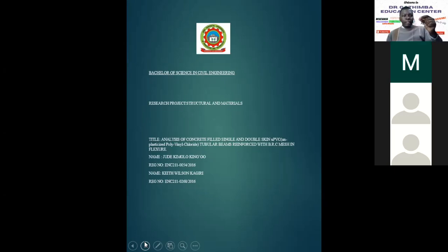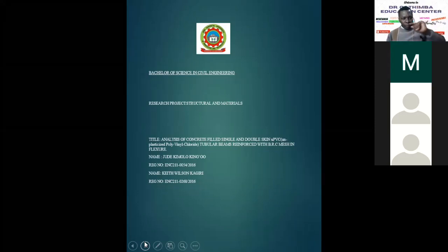So what I was thinking is, could we think of the type? Can the type of the plastic confining material have an influence? Also, I don't know whether he varied the thickness of the wall versus the diameter. So we talk of the thickness to diameter ratio, or I don't know up to what height he went. Did he cover slender columns?